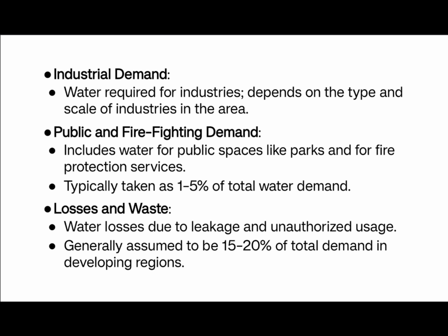Next, public and firefighting demand. Firefighting demand means the water required for fire accidents, and public means water used for parks and some other gardening works and also cleaning of roads, and it ranges to 1 to 5% of total water demand. Next, losses and wastage. Water losses are due to leakage and unauthorized uses.